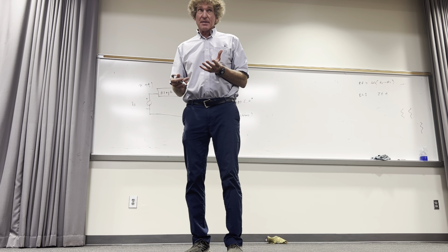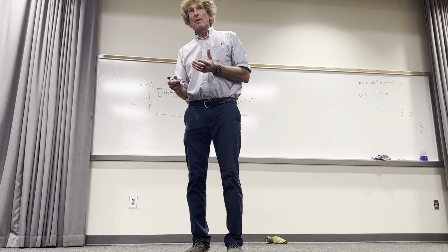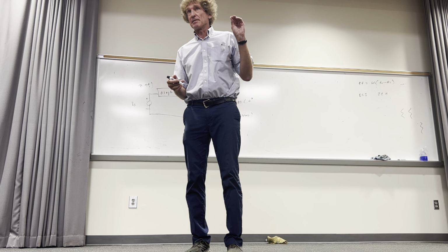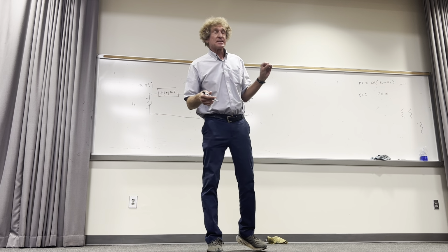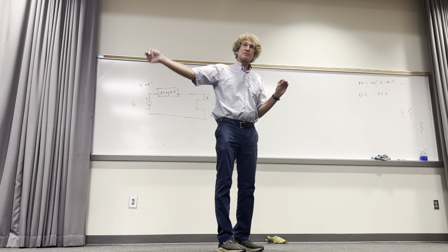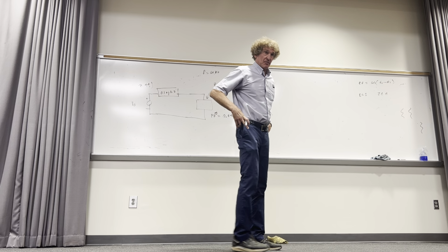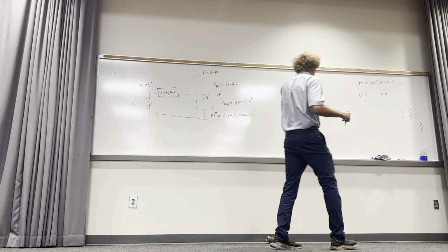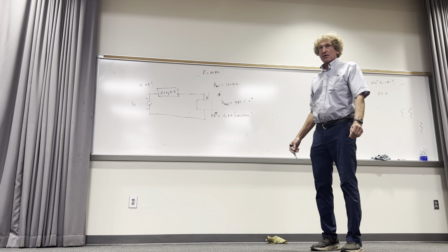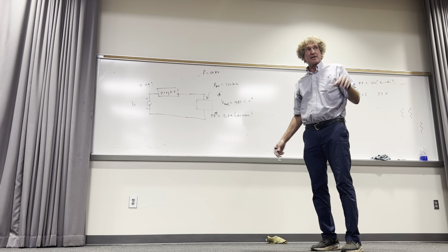Everything is lagging, but the power companies require them to have a power factor above a certain point in order for them to minimize the cost of sending the power to them. Now, the reason that's the case is because the closer the power factor is to 1, the less voltage from the power company it takes to drive the same current. You'll just have to go with me on that one if you don't see it yet. Anyway, this is an old saying, so remember that lagging, the actual current angle is behind the voltage. Now here's a specific example for this one.